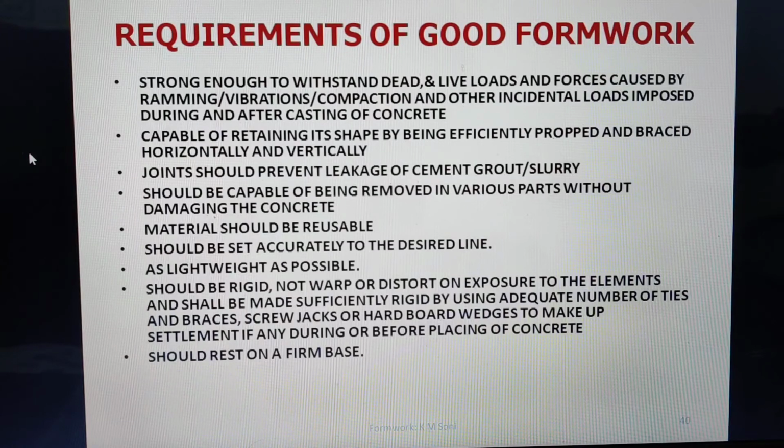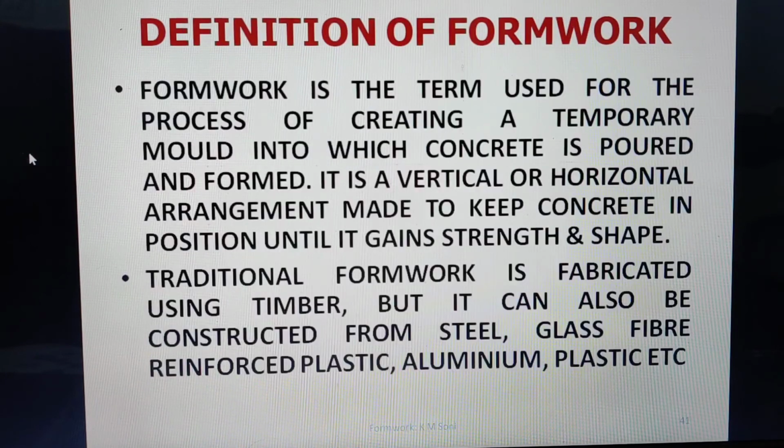It should be rigid also, not warp or distort on exposure to the elements, and shall be made sufficiently rigid by using an adequate number of ties and braces if required. And then screw jacks or hardboard wedges to make up settlement, if any, during or before placing of concrete. And it should rest on a firm base. That is important, and small pieces or anything like that should not be used for that. It should rest on a firm base.